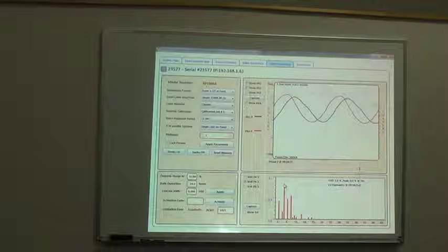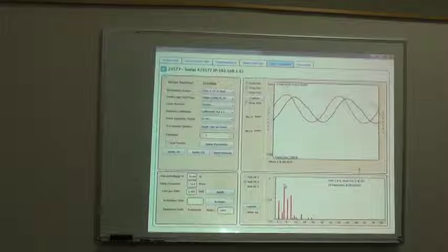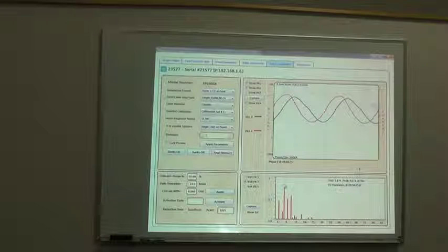So you burn power you shouldn't have to burn. With this technology, you don't involve the fundamental. You just work on the harmonics and the power factor. The way that it addresses harmonics is by managing power factor, balancing and managing capacitance and reactive induction, which is the same thing as managing reactive power. Exactly. You get some inherent savings.